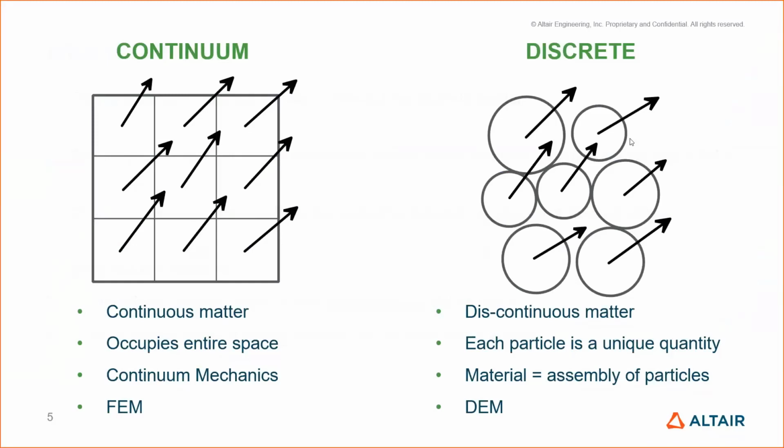In the discrete approach used in EDEM, we're modeling every individual particle as a distinct entity, and we represent the granular material as an idealized assembly of particles or shapes. The overall system behavior results from the individual particle behavior, so this is the DEM method.